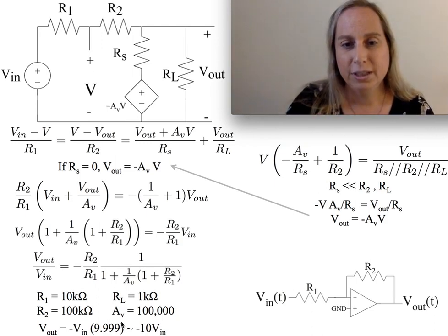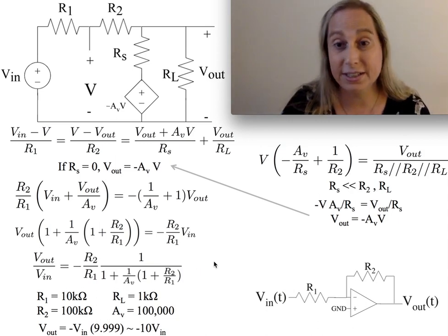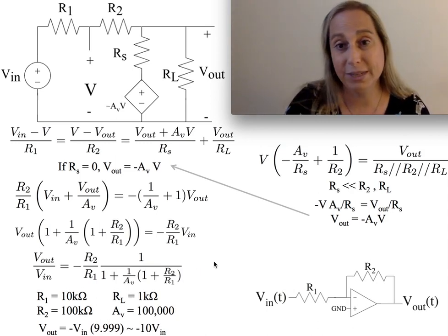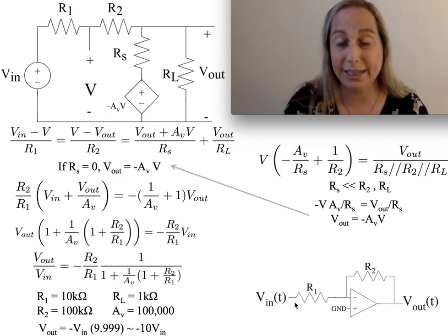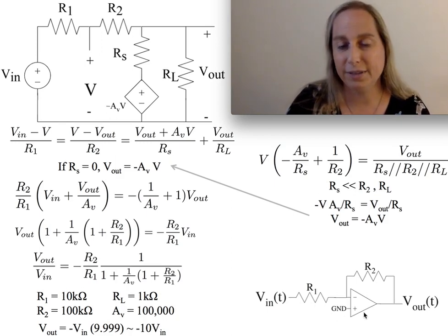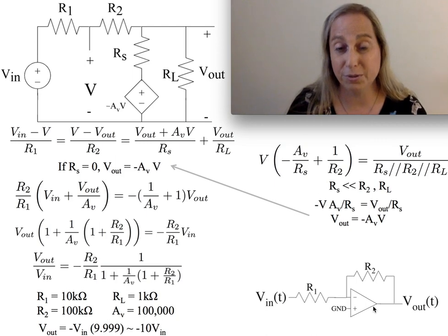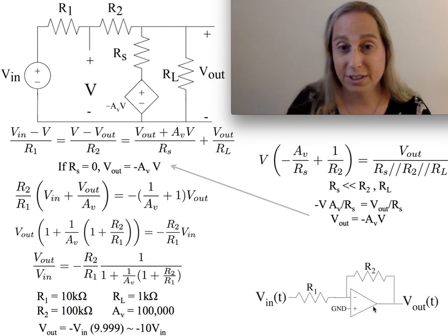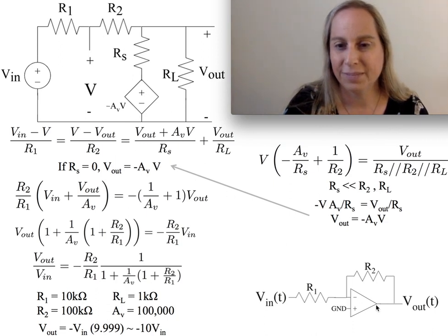Works well. We will see these kinds of things in other circuits in different places, such as this op-amp circuit, where I have an op-amp with two resistors R1 and R2 around it. This structure is meant to be a voltage-controlled voltage source, so it would be modeled very simply by this kind of element, and it would probably be driving some resistive load.